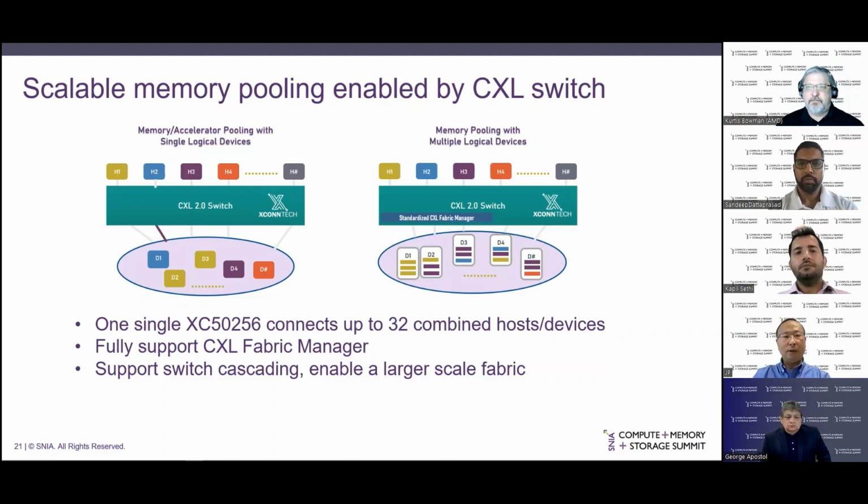The picture on the left is actually the current status, because the processors are CXL 1.1, and the devices are either CXL 1.1 or CXL 2.0, but our switch works with all these devices. And in the future, our switch will work with the MLD device and the SLD device. Also the host can be 2.0. And our switch supports a Fabric Manager, the standard spec-defined Fabric Manager interface.